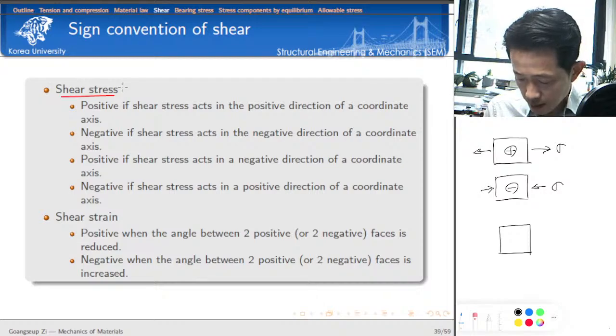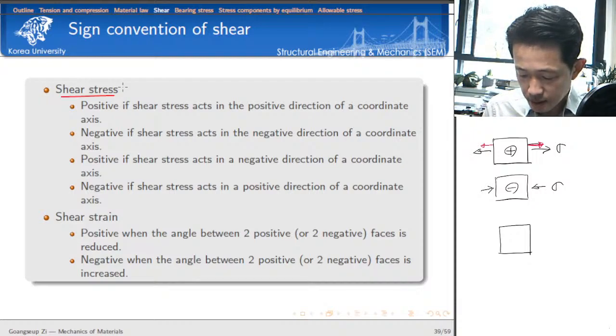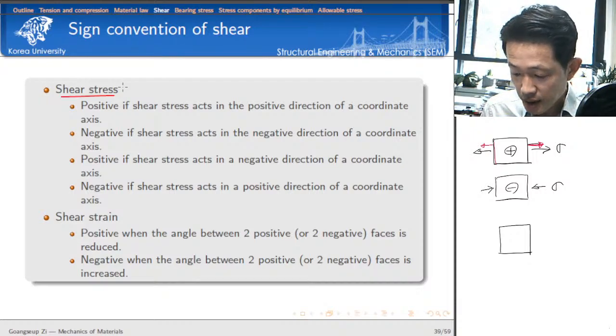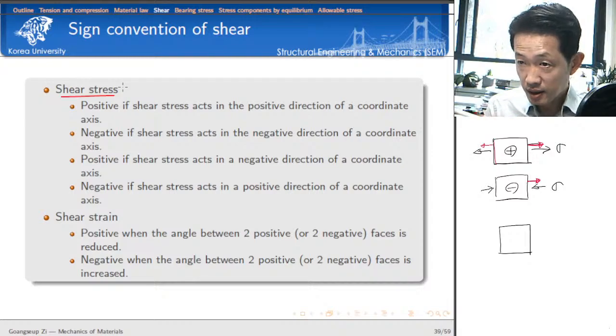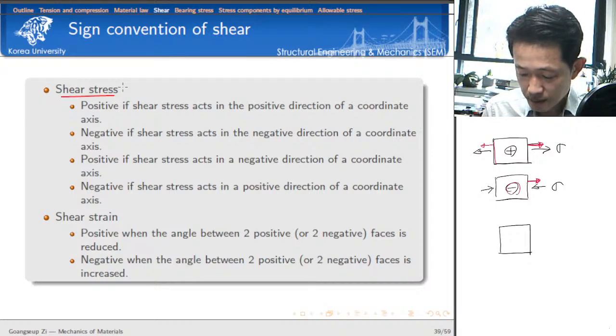As I told you, this is a characterization of the direction of the surface where we measure the normal. This is the normal, characterizing the cross section. If the direction of traction is the same direction, then this is a positive stress condition. But this is opposite, isn't it right? The characterization of the surface is in the right hand direction, but the direction of traction is in the left hand direction. It's opposite. This is negative, the sign convention.